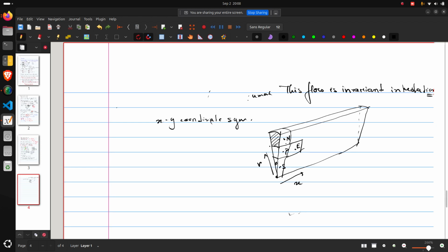It depends on r, so the area becomes a function of r. Even if we have a uniform mesh, the farther away we go from the origin, the more the area will be. So this is the major difference between a 2D Cartesian mesh and a polar axisymmetric mesh.